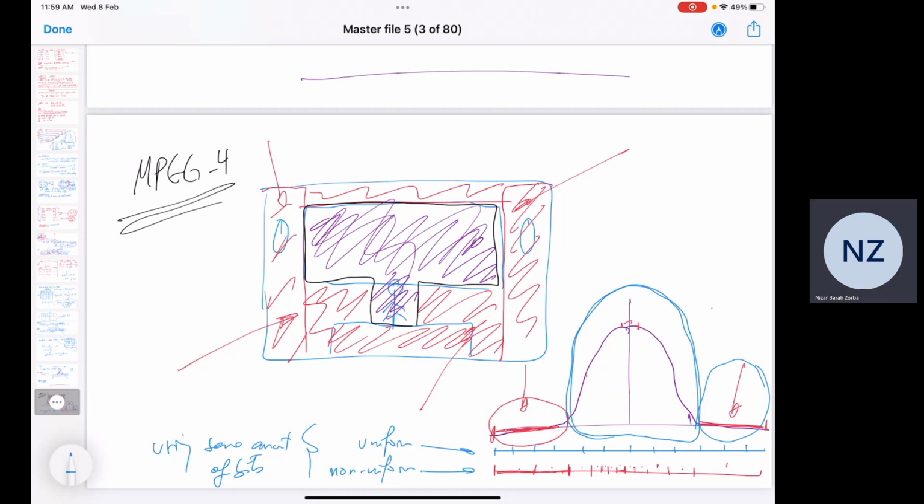Okay. Then they said, okay, instead of that, give them only one interval, which is enough, and give whatever you save here in bits to this part that is changing. That is what you actually need. So it is the same image whenever you would like to download. If you do it over this or over this, it is exactly the same size. It will consume the same amount of bits, same data rate and everything. But this one, if you look at it, you will see that this part here is very clear, this part very blurry. But you don't care because this is what you want. Okay? Well, if you do uniform quantization, you will see it all equal quality.